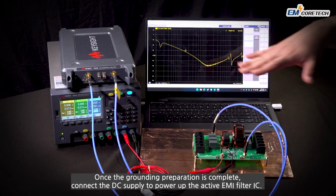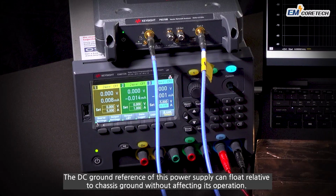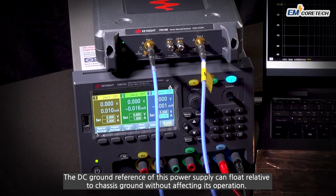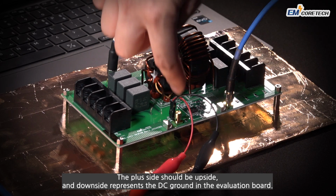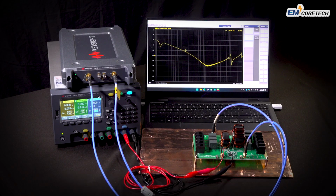Once the grounding preparation is complete, connect the DC supply to power up the active EMI filter IC. The DC ground reference of this power supply can float relative to chassis ground without affecting its operation. The plus side should be upside, and downside represents the DC ground in the evaluation board.